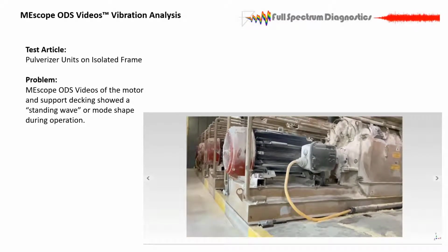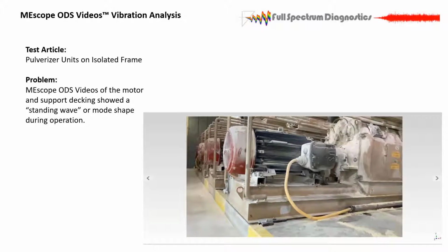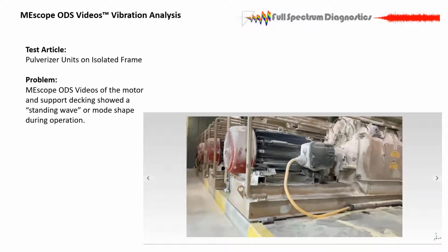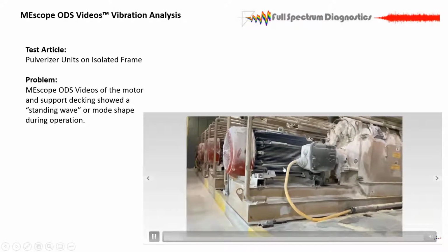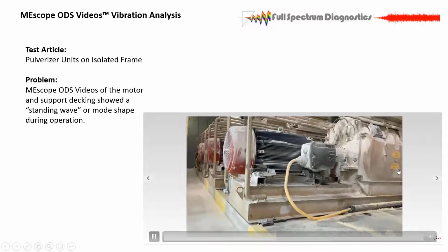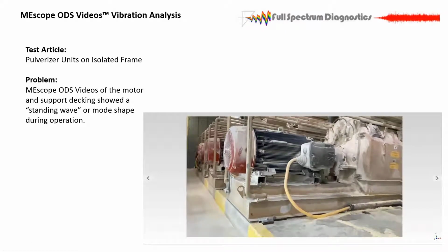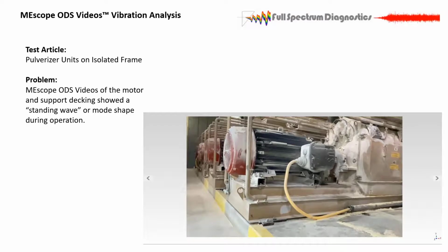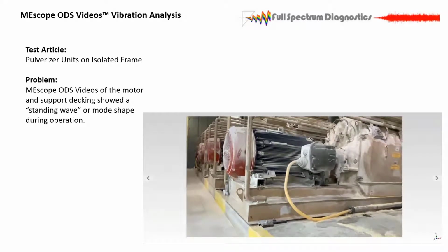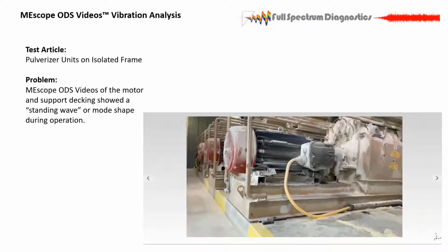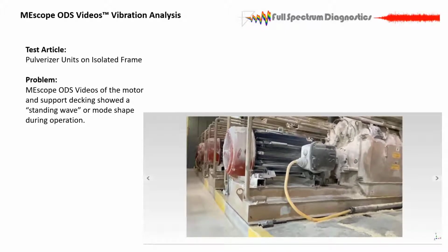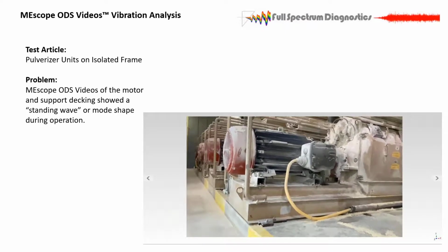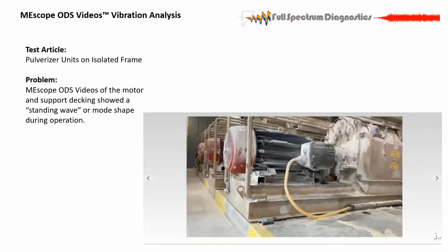This is in the same plant. This is pulverizing equipment. So what you see all over the little dusty stuff is powdered corn. So it's a high-speed motor, 3,600 RPM, spinning a couple wheels, and it's either crushed or sheared or just mechanically pulverized into dust, and it's dropped down through the floor below. So corn comes in the top, dust goes through in the deck below, and it's taken away and goes through some other processing.